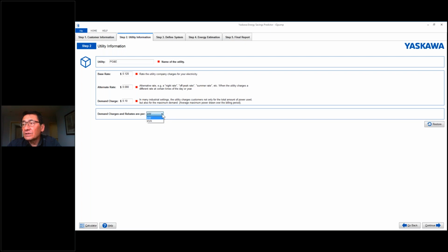If you are being charged in kilowatts, you are not being charged for the efficiency with which you use the power. You are not being charged for the power factor. There may be power factor usage penalties on your bill if your power factor is really poor, below 0.8.